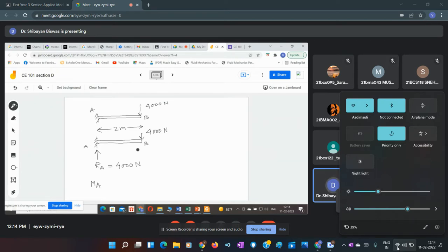So this particular fixed portion, the moments will be generated because that has to be in equilibrium with the system. What you are talking about, the moment at B, the free end, will be 0 because at this point of time no restriction is happening at B. Because B can move freely, there is no moment required to keep it in equilibrium. But the fixed support will not allow the beam to rotate. So that's why the moment will get generated here, because that is coming from the restrictions.